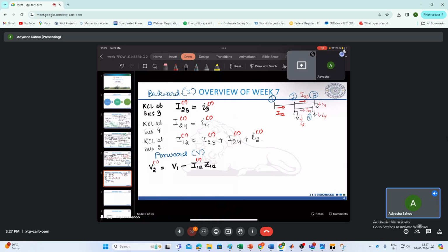Now coming to V3. So what will be V3? V3 will be V2 minus the drop in line 2 3, which is I23 times Z23.